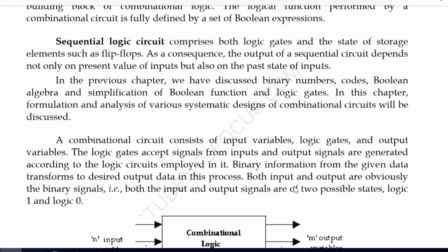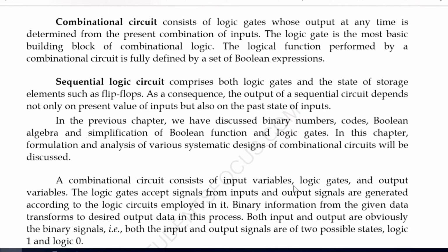So there is a need for a feedback system in sequential logic circuits. Why should there be a need for a feedback system? In order to store the state. In order to store the state, we need a storage element and also need to provide feedback for the past input. So a sequential logic circuit consists of a feedback element which acts as a storage component.